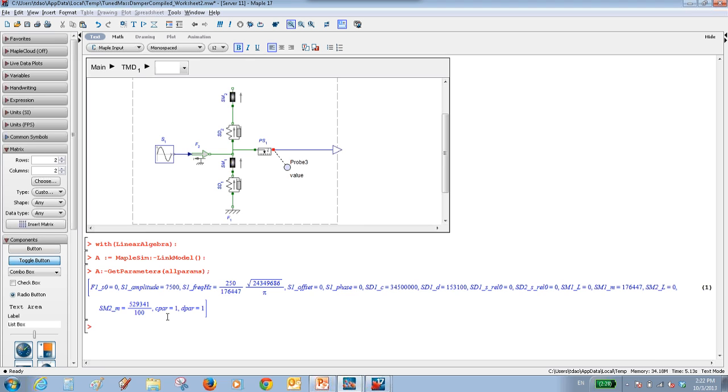In order to generate the C code from the model, we are going to call the command called get compiled proc. It is one of the API commands in the MapleSim package. This command generates the optimized C code from the model and assigns it to the variable that I defined called cproc. I will also define the solver that I want to use.